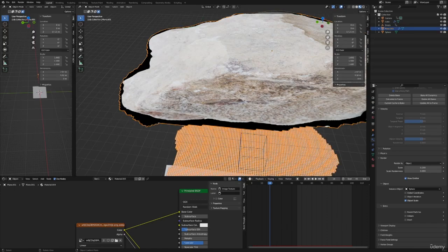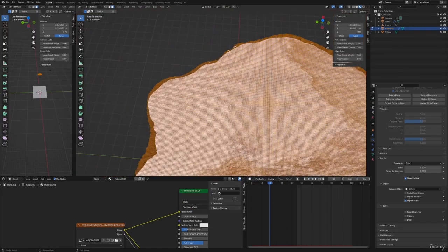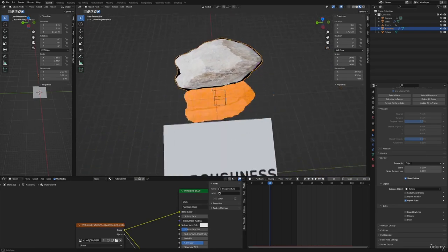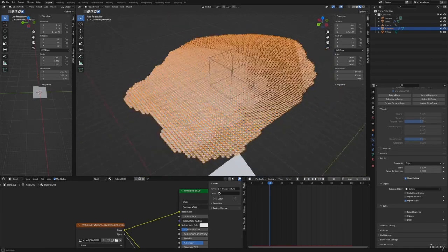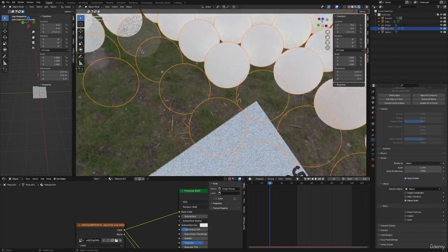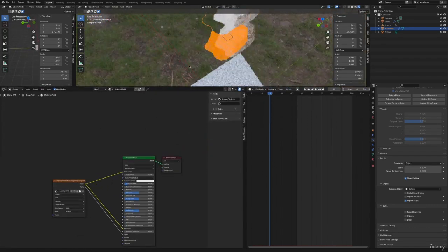If we go into the material preview here, you can see these black renders here, and that was just practically the transparent PNG in a square plane, which I then subdivided. And then I simply deleted the faces on the outside, roughly, so that an unnecessarily large number of particles are not emitted here. When I say activate now, you can see that there's still a few particles out there that are transparent, or this particle here, for example, which is almost completely transparent. The question here is, of course, how can I actually render this now?